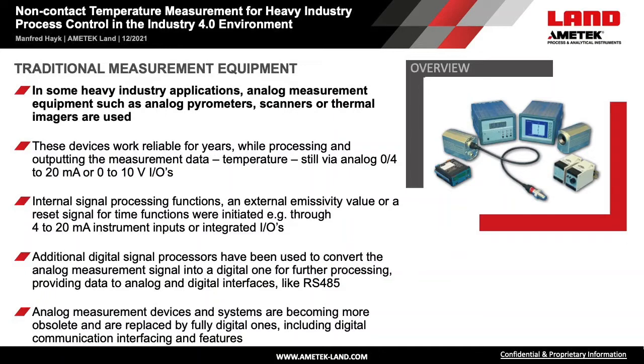Internal signal processing functionalities, an external emissivity value or reset signal for time functions were initiated, for example, through 4 to 20 milliampere instrument inputs or integrated IOs.